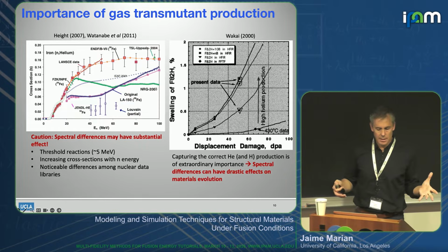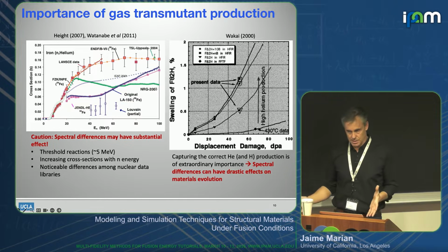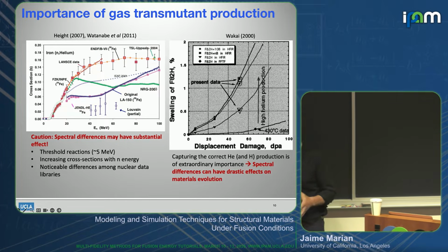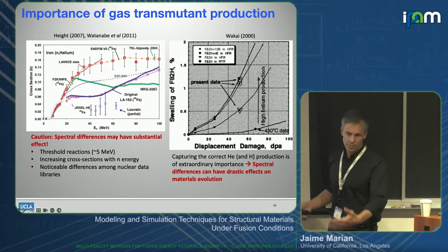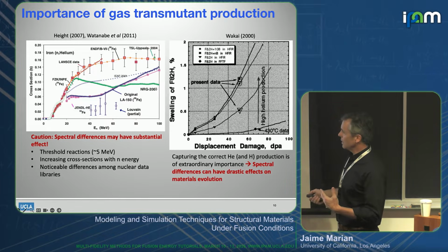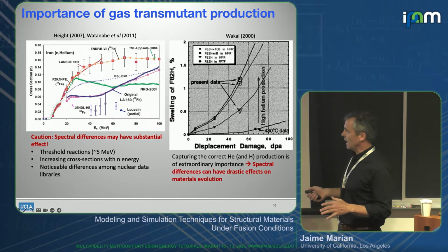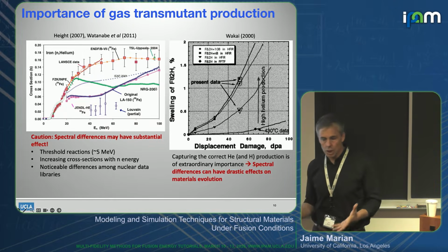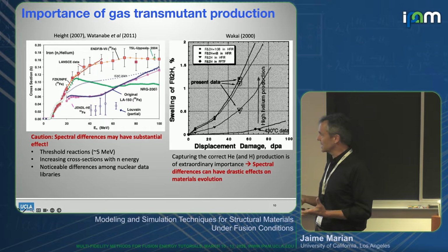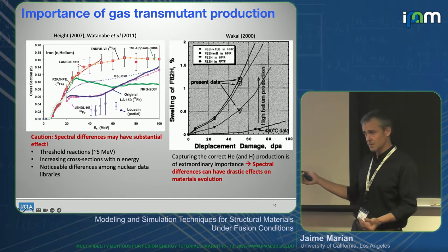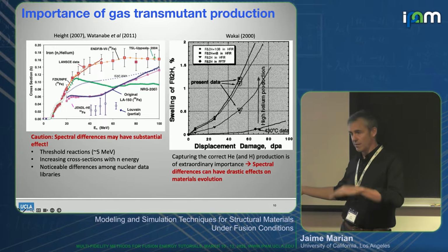These will become gaseous impurities, and as such, they will form bubbles. They will coat grain boundaries. They will go to precipitate interfaces, and effectively, they turn your materials into a sandy, grainy mess. And I mean it. That's one of the reasons that leads to their low fracture toughness.